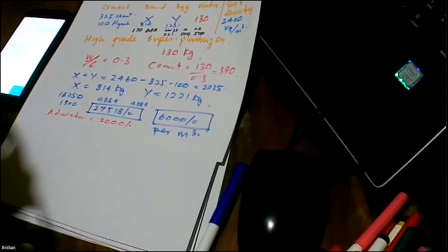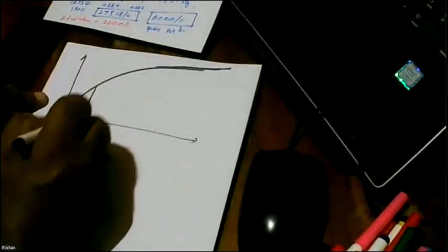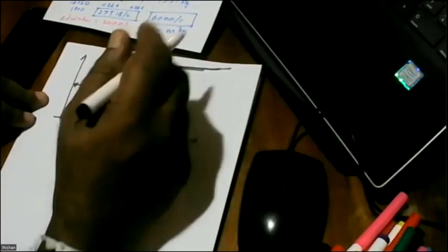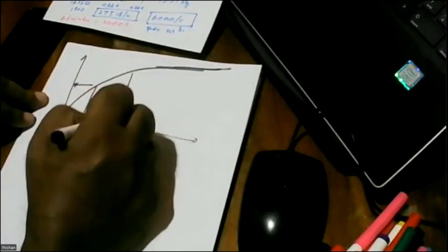And then what you have to do is you have to do a mix like this, and the strength development curve is going to go like this because it's going to rise, right? And so if you are going to do the transfer at 4 days, we'll have to find the strength, and then once you do the transfer, after a certain age, you can move it and even launch it and apply stresses.